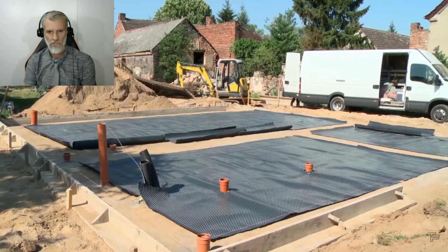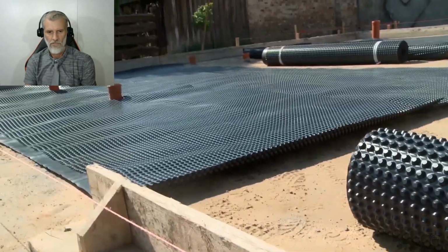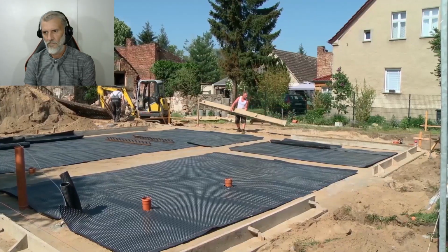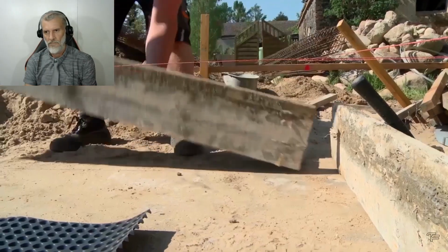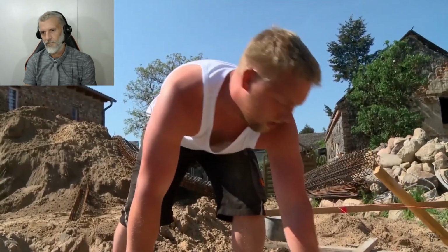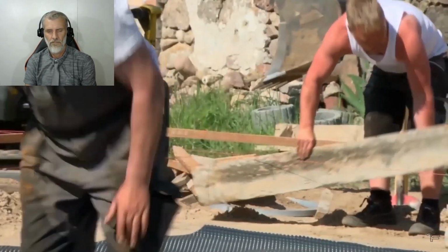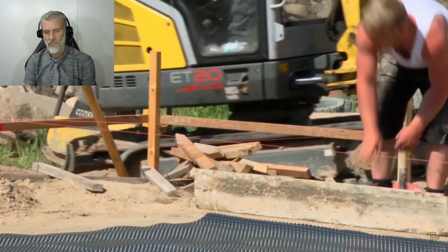Then the formwork comes. The formwork defines the dimensions of the floor slab. The 8 measurement points, the nails, are the default. The formwork is placed exactly to the string. Precise work is extremely important here, so that the edges run exactly straight and the base plate gets the right size.